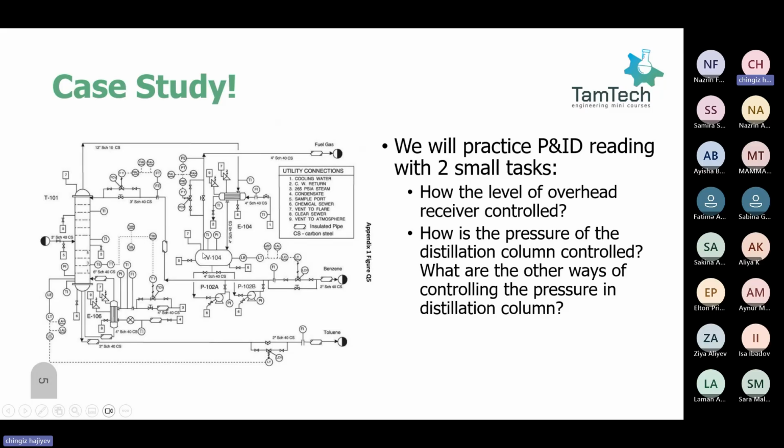Let's say you have an emergency situation in the downstream of the equipment. For example, fuel gas goes outside the battery limit, you see this line shows the battery limit. Something happened in the downstream process and we need to cut the fuel gas. We need to have a kind of emergency exit, some line for that.